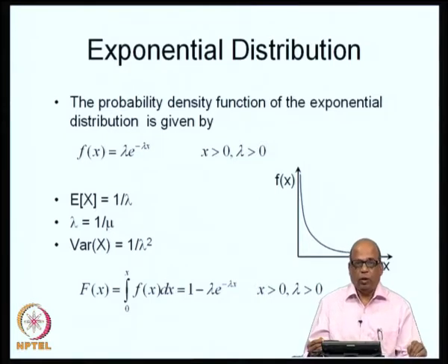So, log normal distribution is mostly used, as I said, for monthly stream flows, conductivity, evapotranspiration and so on. But there are many situations where we will be looking at time between critical events. Let us say the time that has elapsed between high intensity rainfalls, or the time that has elapsed between two critical floods of a given magnitude. Whenever we are talking about such variables, then log normal distribution is not generally suitable.